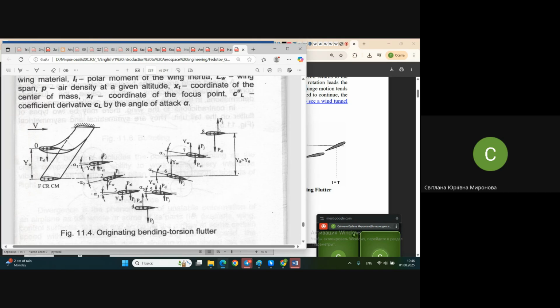Moreover, as soon as you change angle of attack, the point of center of pressure and the resulting force itself may float a little bit. There is another point which is called focus, and this focus is stable with respect to the nose of the airfoil, let's say. It's always in the same position. But center of pressure is a floating point.